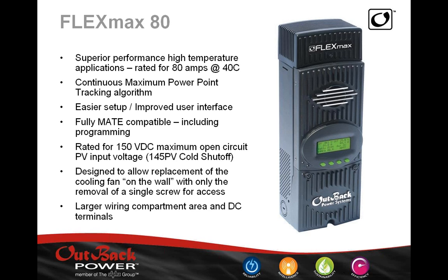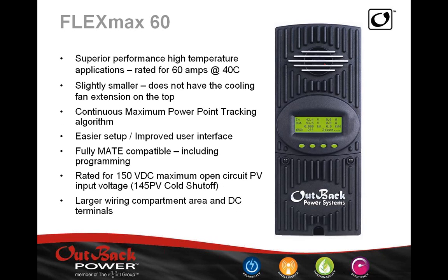Now, these charge controllers also have a secondary output, 12-volt output, at 200 milliamps, and that can be used to implement, again, any type of logic, just like inverters. But it is only 200 milliamps, not 700 milliamps, like the FX inverters.